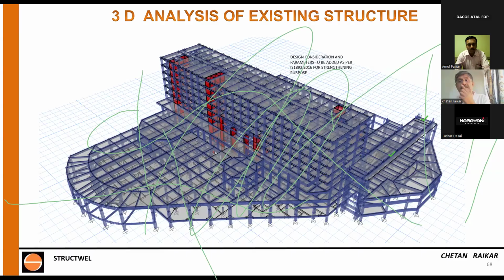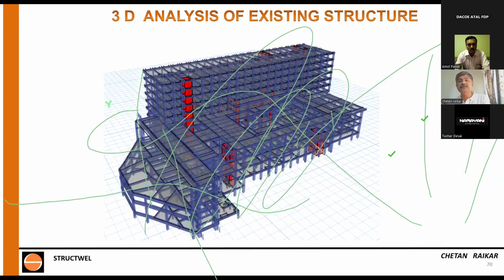So what you need to do is prepare RCC drawings of the existing structure by physical measurements or any other technique. Try and find out the maximum level of reinforcement that is available easily with cover meters, and do a regression analysis. This is how the structure is. I'm sure many of you are structural engineers, so I need not elaborate more on this.